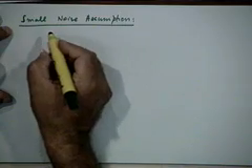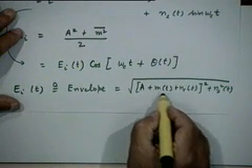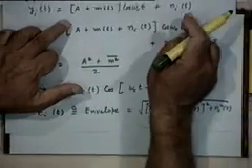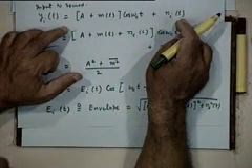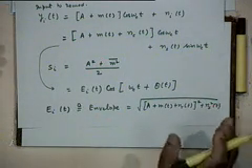Basically, what is the small noise assumption? That is essentially to say that the signal power at the input is much greater than the noise power at the input. That is, the signal is much stronger than the noise. Is this justified in practice? Typically, yes, though it depends on the kind of situations you are working with. In broadcast applications, it is justified, because you have to maintain a good signal to noise ratio.